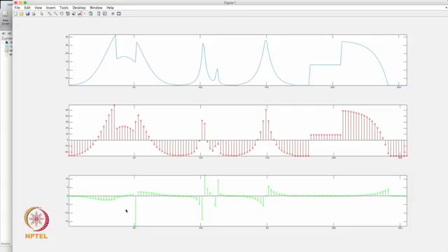This is a one level decomposition indeed. Now, if you look at the signal, there are discontinuity locations at these points here. Let us pick one discontinuity location here. I have a discontinuity location around this point, and correspondingly in the detail coefficients I see a spike, and that is true for other discontinuities as well. Of course, the first thing that you should notice is that the resolution of the approximation coefficients in time has fallen down by a factor of 2.